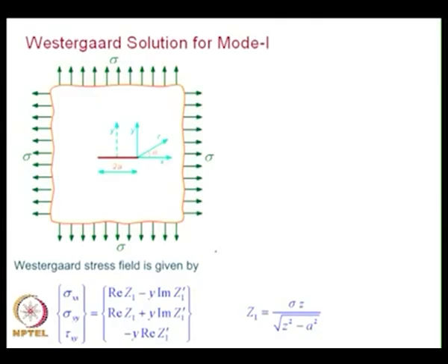See, what we have got here is, if I take the stress function in this fashion, it definitely satisfies the stress free boundary of the crack as well as biaxial loading at infinity. This stress function takes care, but it also says tau xy equal to 0 along the crack axis.